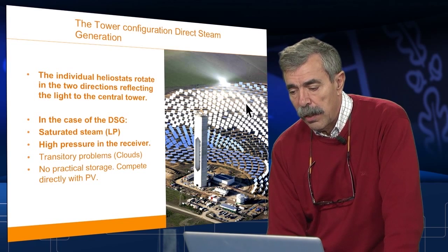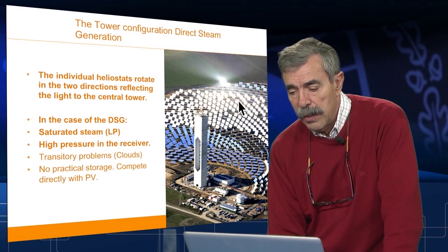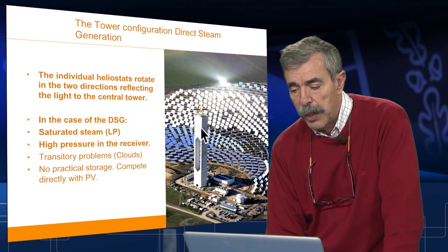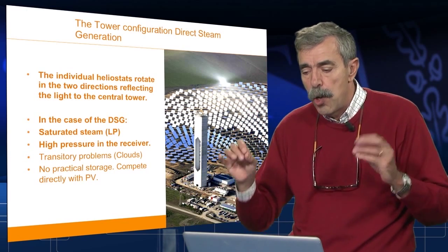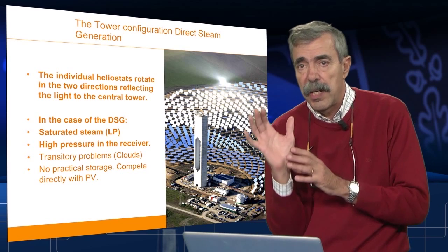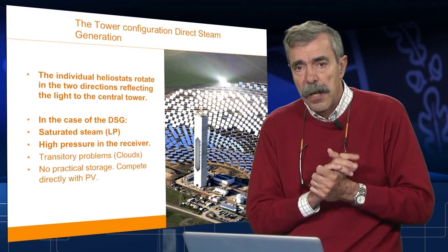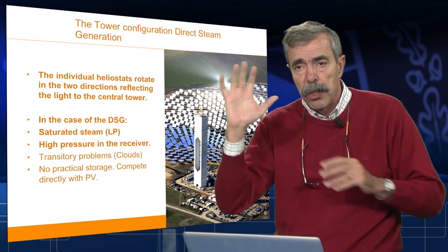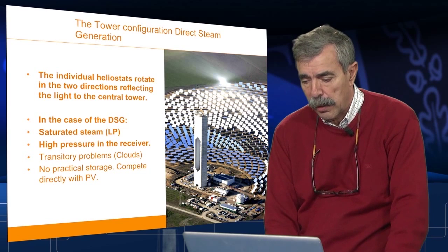Since the relative position of a heliostat versus the target differs from one heliostat to any other, the angle to obtain the light concentration on the target also has to be different. So in the whole solar field there will be no two heliostats having the same angle. Each one has to have a different mathematical law to do the job, I mean, to adopt the right angle to reflect the light onto the target.